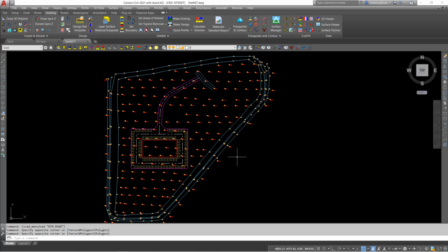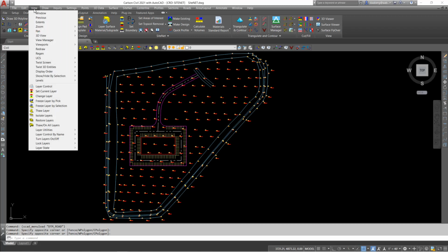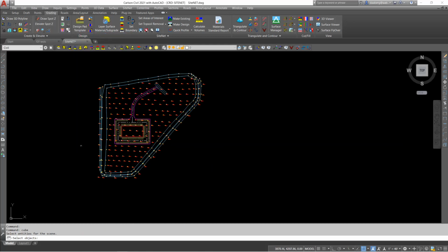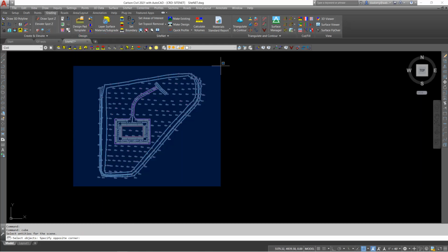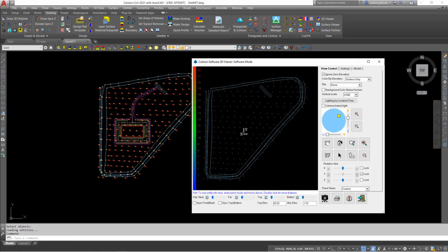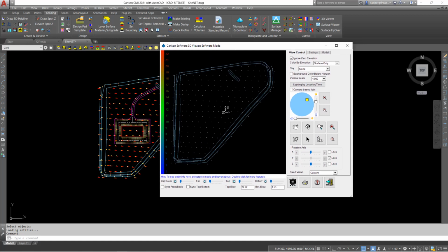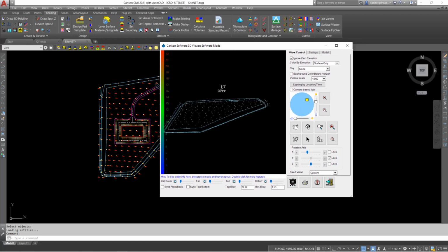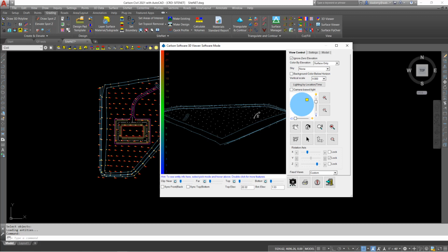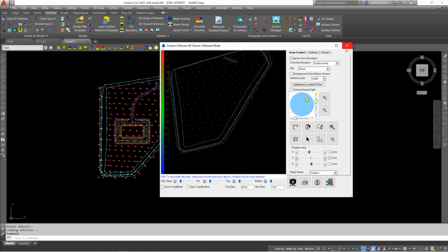into 3D design elements. Now, throughout this demonstration, I will be using the 3D drawing viewer to examine entities as I draw them. Now, to take a look at what we already have, you just simply select the entities you'd like to view, and you can see that the design elements, the parking lot, building, and access road, do not appear because they are not elevated entities at this time.